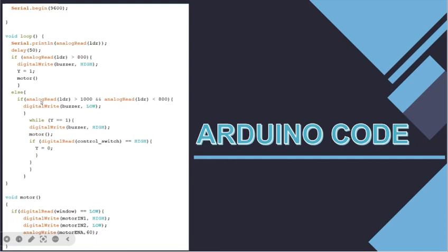Now if we go back to our previous portion, we can see while y is 1, the buzzer will be high, and if the control switch is manually made high, the value of y will be 0. It means once the buzzer is triggered, the buzzer will stay high until someone manually gives the control switch a high value, and only then will y become 0, and again the normal loop will be running. So that's all about our code.